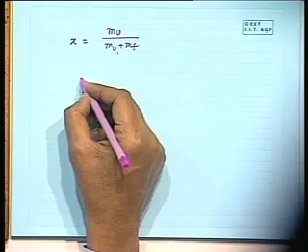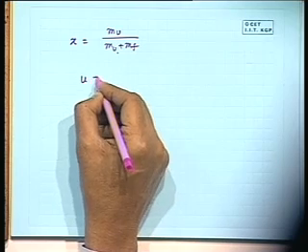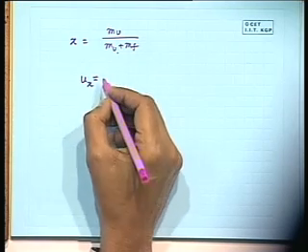If I ask you what is the internal energy, enthalpy or entropy of a mixture of water and steam at a particular pressure and temperature, you will ask me to tell the composition, then only you can tell, because I know these values for dry steam at that pressure and temperature, at this end of the curve. I know this value for the saturated liquid at that pressure and temperature. But if you tell me the value of X for a mixture, then I will tell you, and this is simply a class 4-5 level calculation. If you define that, I think you can immediately write all such properties: the specific internal energy for any quality or dryness fraction X is what?